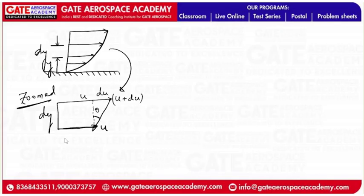So if I am trying to say tan theta, or since the angle is very small, I am saying d theta. Not even theta, I am saying d theta, because the angle is very small, right? Angle being very small, that's why I am bound to say this is d theta. So tan d theta will be this distance du. Now this has to be a distance, but du is only speed, so I have to multiply it with the time dt, and this is the base, which is dy.